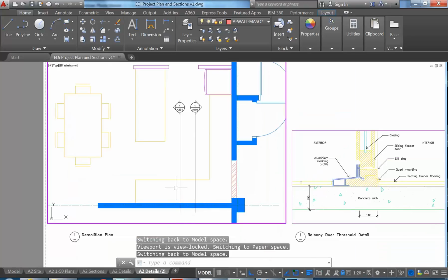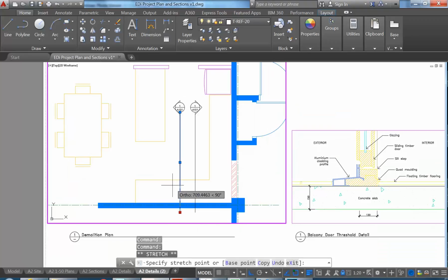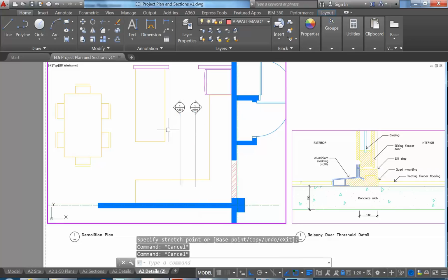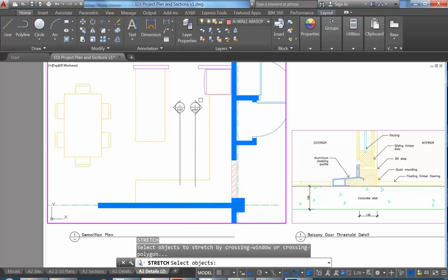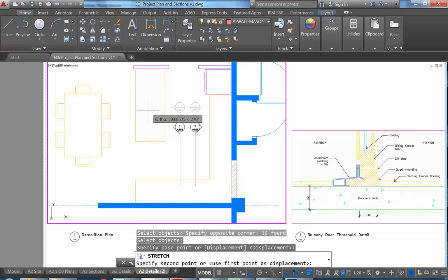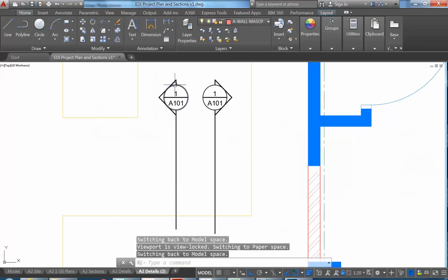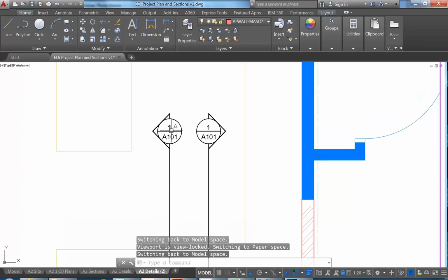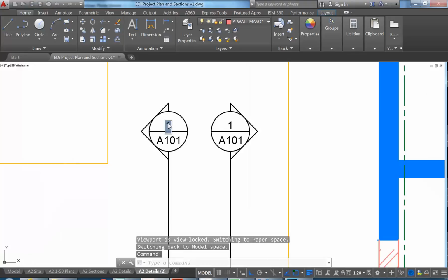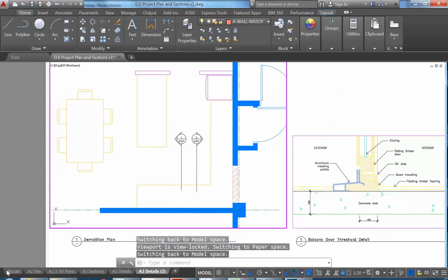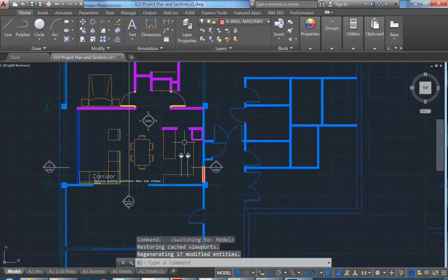So I've got those two references. The lines there could even be shorter, just to make it a bit neater and more presentable. They just need to be touching something that they're cutting, and they maybe don't even need to be quite that long. It looks a bit messy the way it is there, so I could shorten those even further. Something like that. Okay, but it's really important that you have the referencing set up properly for drawings like this especially. Okay, so I've done that referencing, and now I can start projecting my drawings.